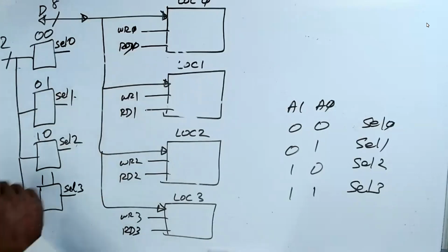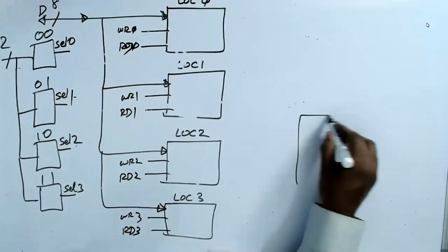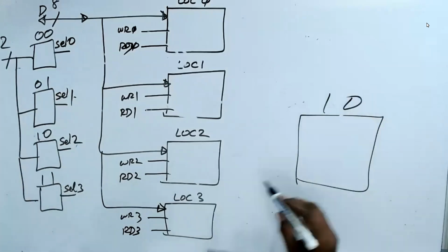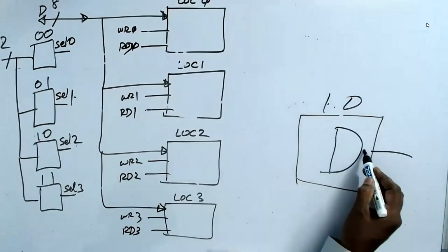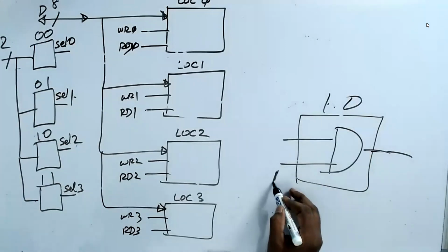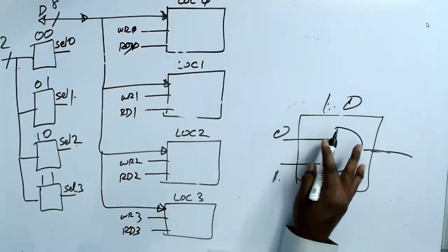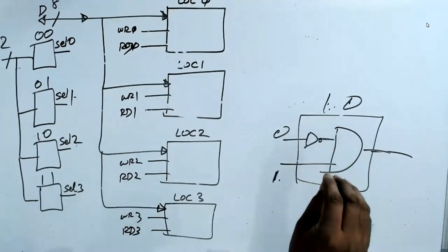This you know, how to solve this. We have discussed the combinational logic block. If I have a block whose name is 10, the output is 1. So I have two inputs, a two-input AND gate. One input is the MSB, and for 0 I have an inverter. That's it. This we discussed in the combinational logic block. Remember that, that's why I told you repeatedly. You understand this.